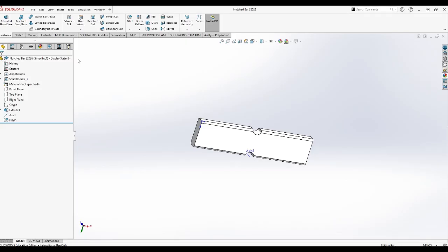For any finite element analysis, there are three stages. The first stage is called pre-processing, then you have the solution, and then the post-processing. The pre-processing means, first of all, defining your model geometry. In this case, part of the pre-processing has already been done for you because you have been given the part file. If you have not been given the part file, then you have to start by actually drawing the sketch and then creating the solid model, and that will be part of your pre-processing.